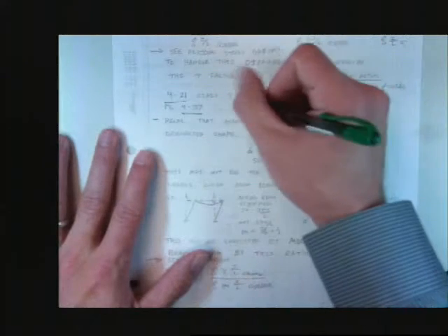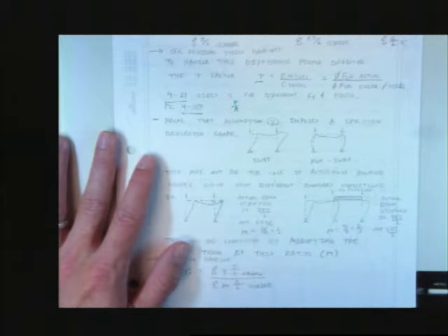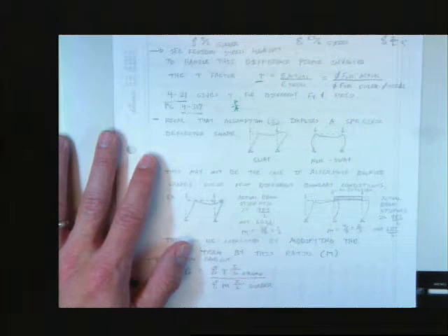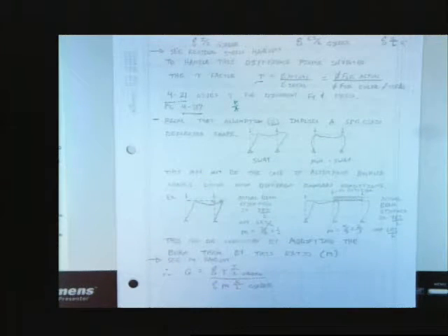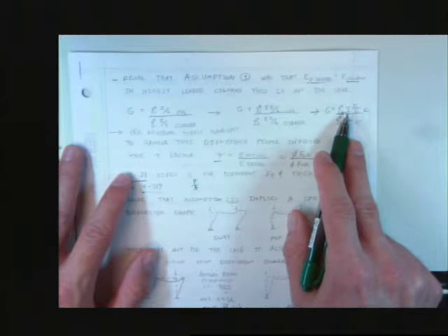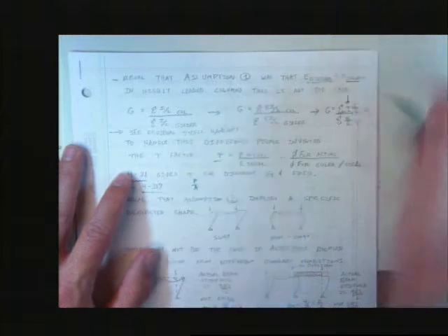This means all I need is P over A. All I need is to look up the stress on my column, and I go up and look at it in the chart, and it gives me a tau factor. Tau factors are going to be anywhere between 1 and very low numbers. What they do is they modify the stiffness of your column. You'll have a tau factor for each column, and you're going to have a tau factor that goes in the numerator.